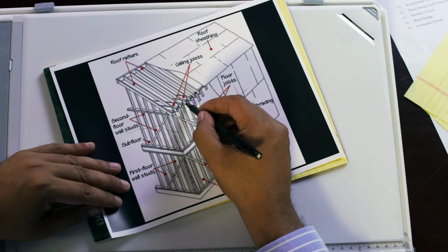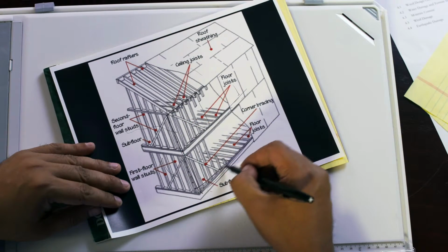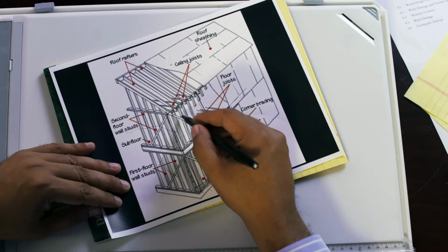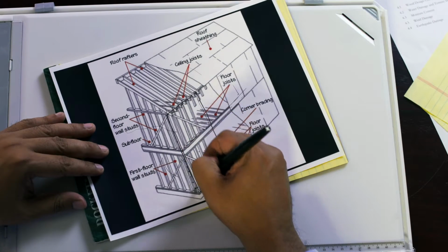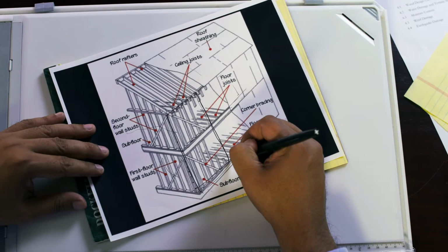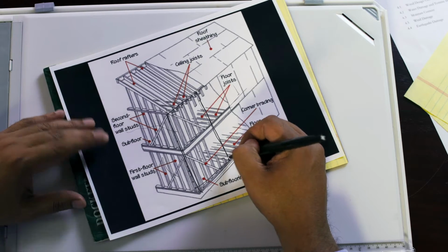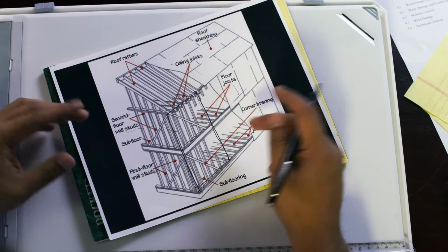If, for example, let's take this design, let's say that my architect wants to create a bay window here, and he wants to have the height of the window going up 2 stories. Yeah, you can do it. I didn't say you can't. You're just not going to be able to do it in wood. You'll have to put a steel column over here and a steel column over here. So it can be done, but then you've got to go with a different material. You can't do it with wood because it's too much.